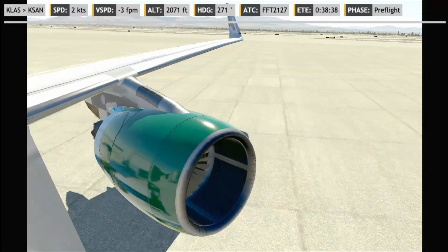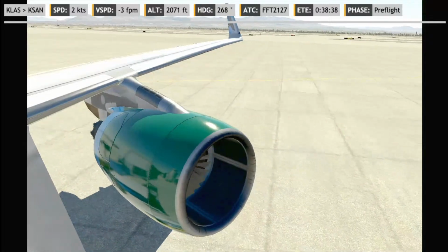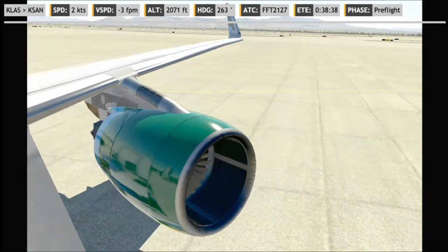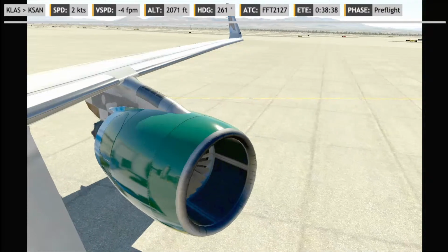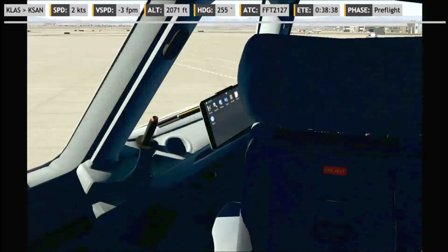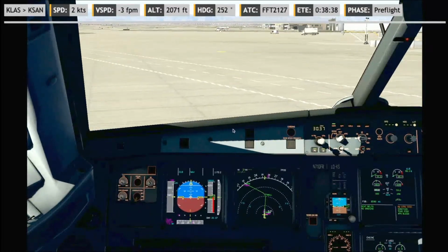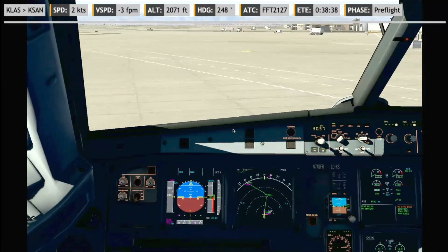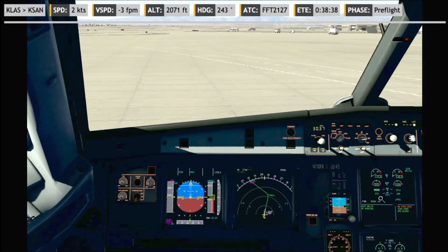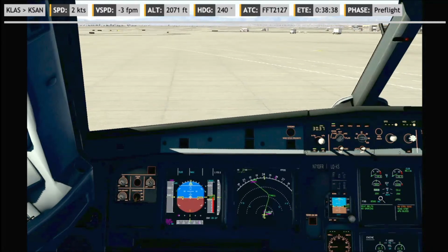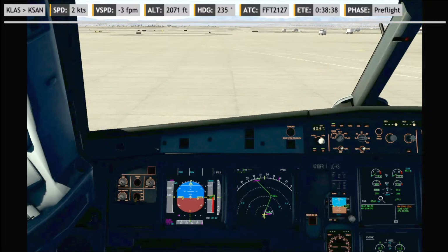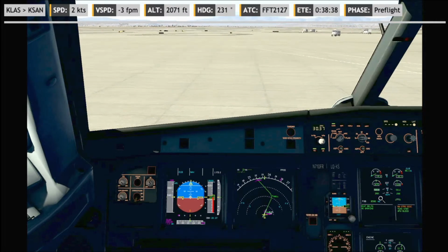So you have 3 hydraulic systems in the Airbus, one powered by one engine, the other powered by the other, and one powered by electrical systems. It's really an oversimplification, but if one engine is not running and there is a difference in pressure between the 2 systems, the PTU will use one system's hydraulic pressure to power the other. That's basically it.